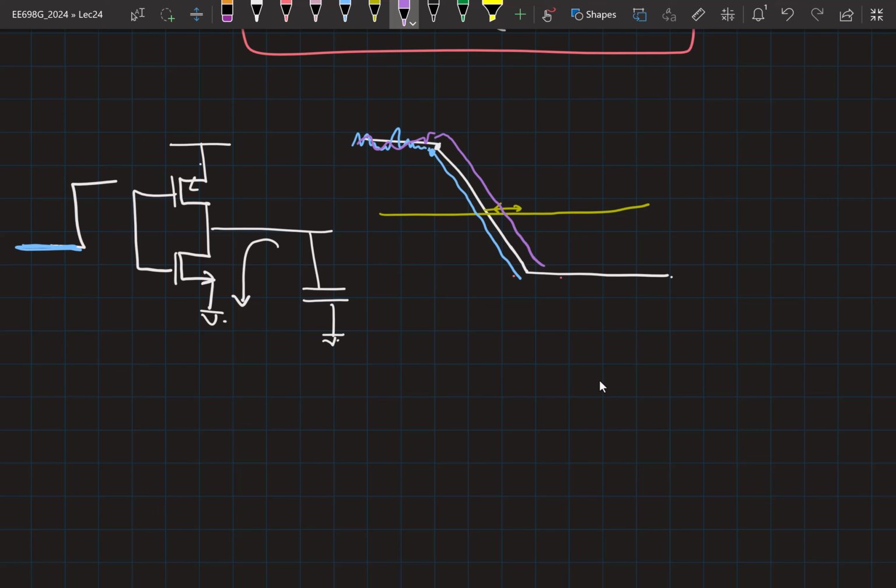Yeah. So it's because of the PMOS. So that PMOS voltage becomes the initial voltage for the capacitor, right? From where you start to discharge. Is that clear? So this way both NMOS and PMOS are going to contribute to the noise of the capacitor. Now the other reasons you said, noise during subthreshold conduction, the CGD, supply noise, all of those are true, but I wanted to show you that even if noise was not there and the transistor was ideally in cutoff without any current flow, you still have these problems.